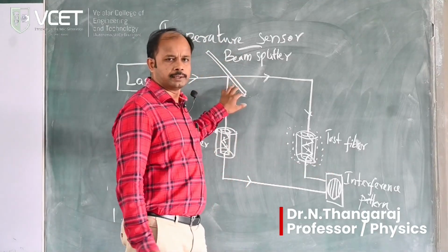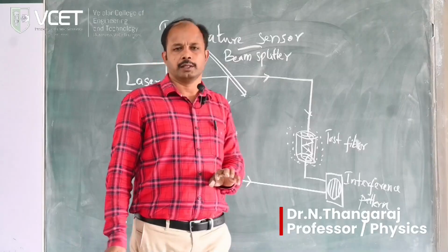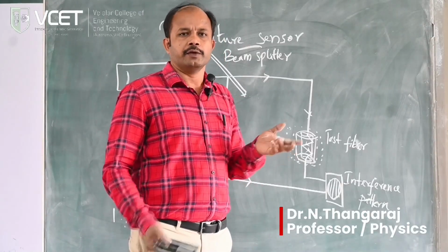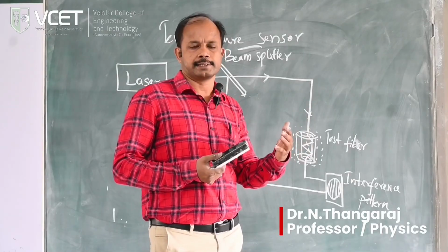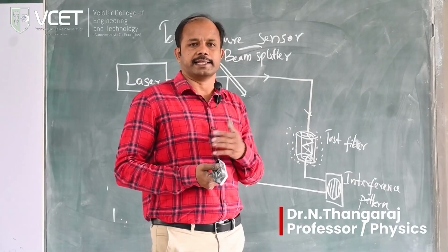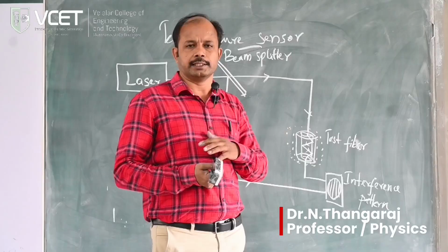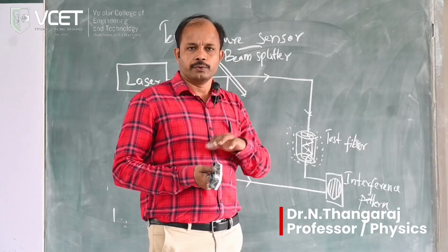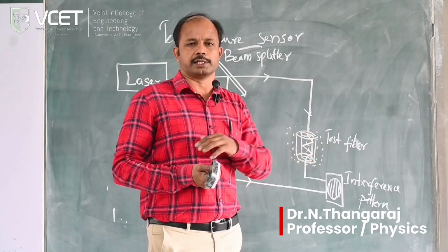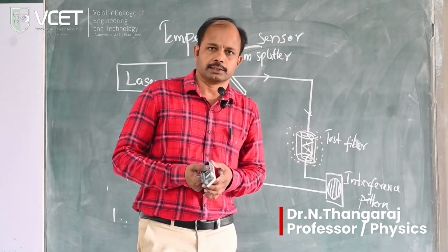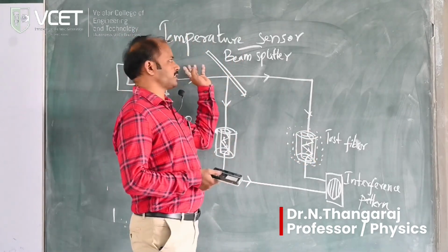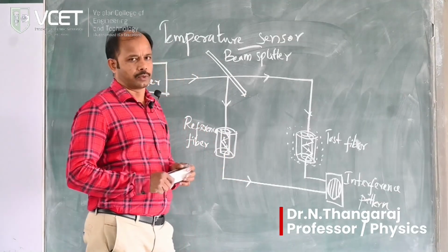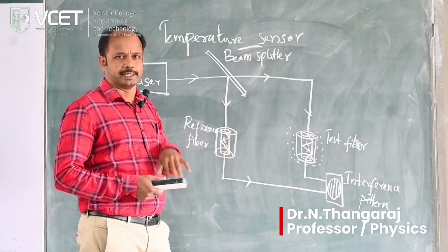It is one of the applications of optical fiber. One more application is the displacement sensor. In this displacement sensor, we can measure the distance by analyzing the intensity. If the intensity increases, the object is moving towards the detector. If the intensity is reduced, the object is moving away from the detector. Okay, there are two applications: one is the temperature sensor, another is the displacement sensor. In the next class, we will see the